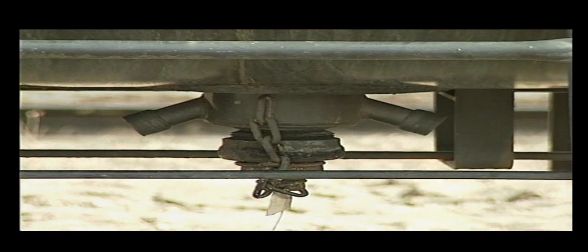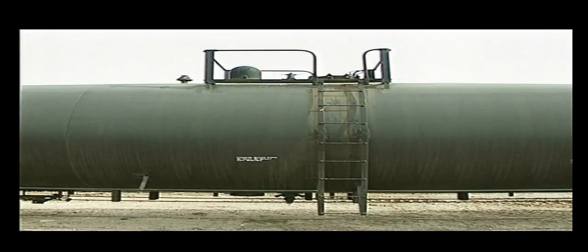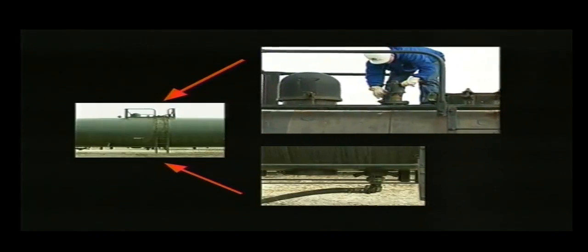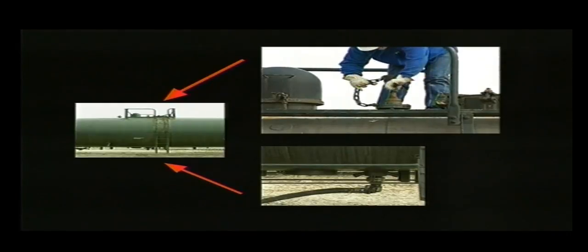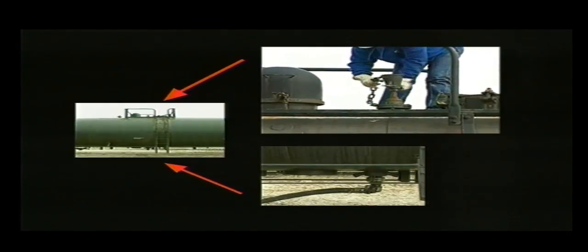The final bottom outlet valve that we'll discuss is the top-operated bottom outlet. On the bottom of the car, we have a standard outlet extension cap and plug, but the operating mechanism is on the top of the car. To operate this valve, go to the stuffing box cover located on the top of the car on the stuffing box nozzle. Invert the cover over the top of the operating rod. Turn the handles of the cover counterclockwise to open the valve at the bottom of the car.